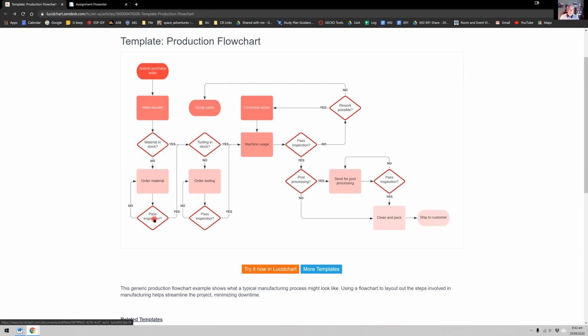For instance, every box of resistors that came into the company was opened, and someone would check the resistors. They would pull out some of the resistors on the band of resistors, and they would check that they were the right color code. Then they would actually test some of those resistors. There was a specific number that they had to test with a multimeter to check the resistance was fine. And of course, if it was fine, then it would just go through the process.